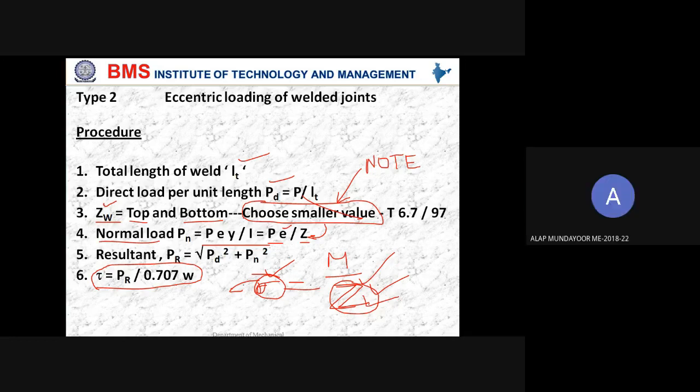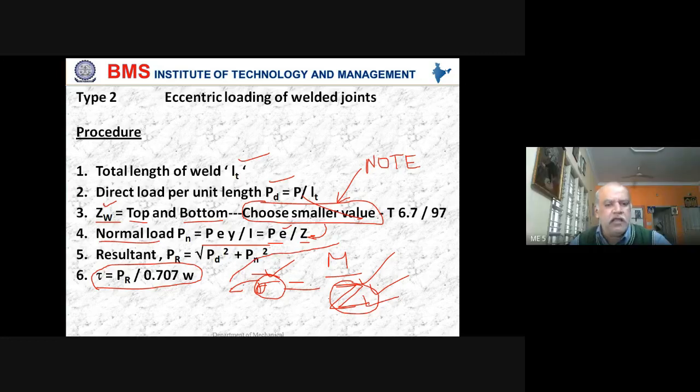If the material is fixed, then we cannot change the stress value, so we have to increase the section modulus. Because if you choose C40 steel and a factor of safety of two.